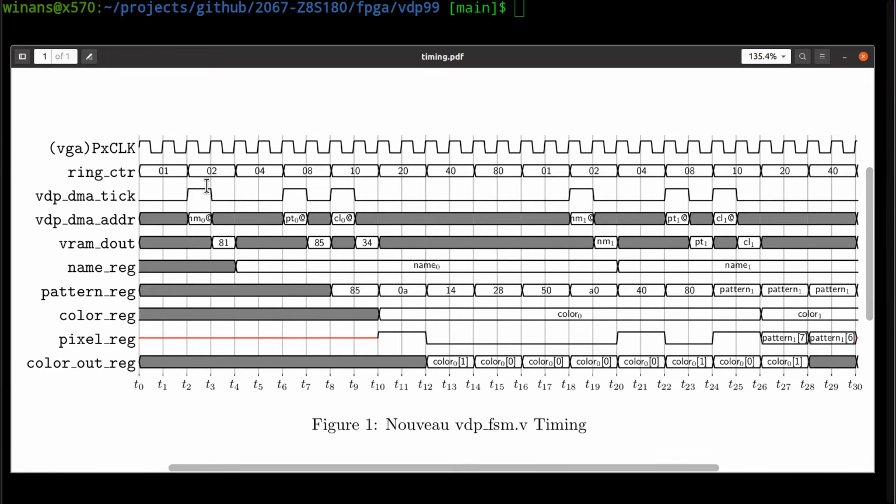We already talked about how the video RAM works in the VDP in another video. So we know that the CPU can do read-ahead logic and stuff in case the CPU wants to read, but the state machine also needs to be able to read from it. The state machine has to get what it wants when it wants it, or we can't render the screen.